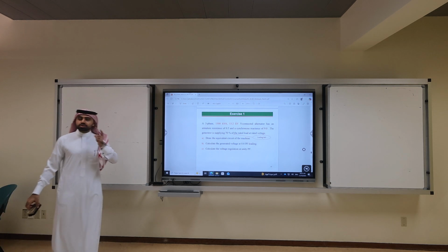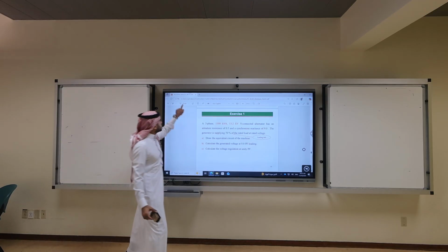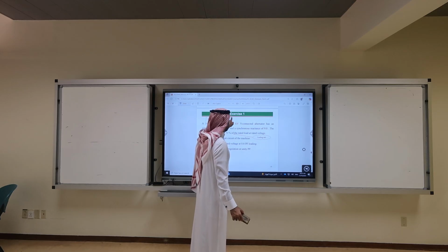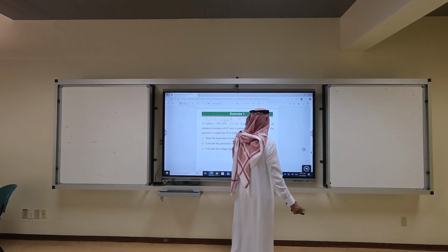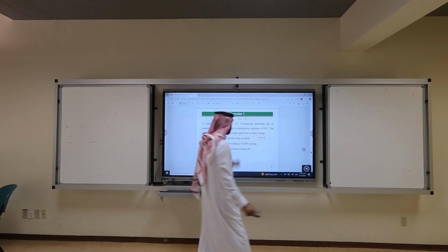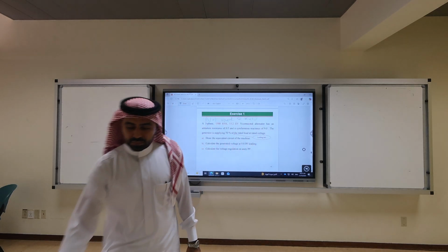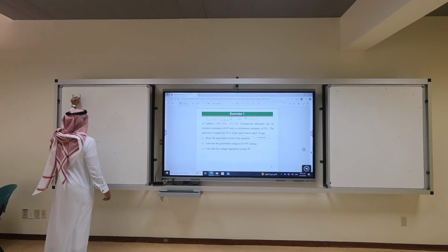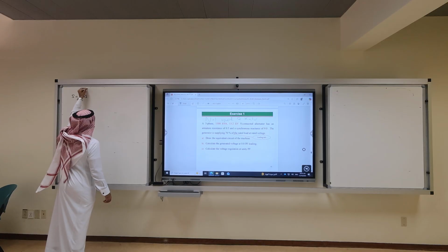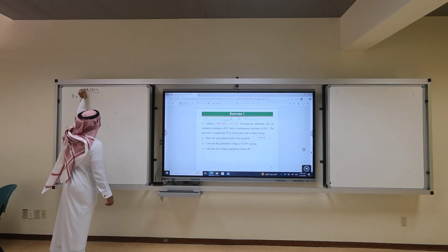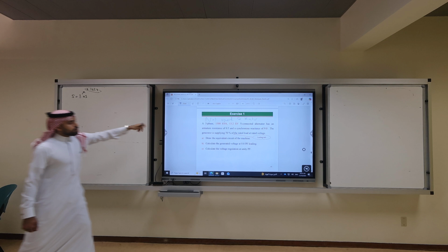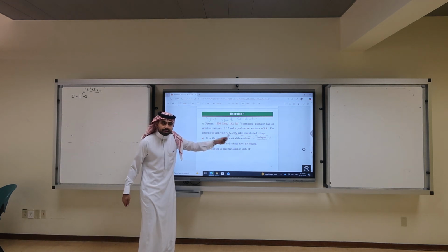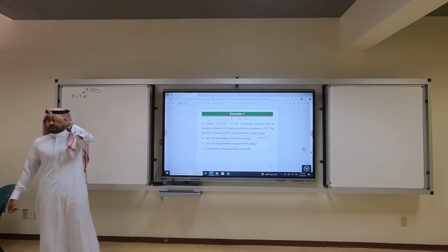1.05. Always use rated. So this problem is not, we are not operating at rated. In fact, we're operating at 70% loading. So what is the S? 1.05, which is 0.7 times 1.5. So nameplate says rated, but are we loading it fully? 70%. That's the most important part of this question.